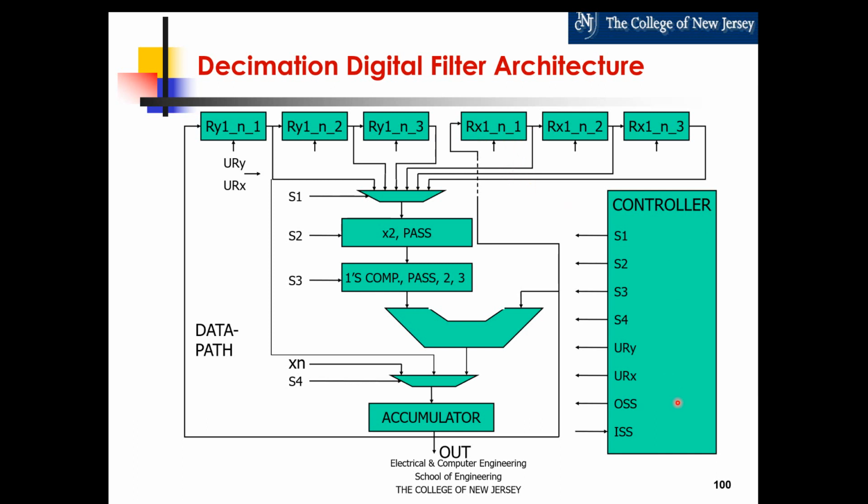Then I have my controller here, but before I determine what are the inputs and outputs of my controller, I develop the data path some more. So I know that all these different quantities are going to be operated on, so they need to be inputs into the overall data path, and I'm going to manipulate them according to the state and my state sequence.